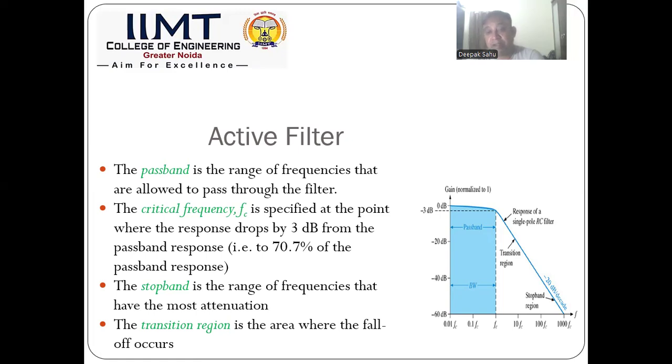And now there is the roll-off factor, which is actually our main issue, because the roll-off region after the cutoff frequency has to be very narrow, so that it does not incorporate or absorb any noise from nearby systems. So the roll-off factor needs to be high. The higher the roll-off factor, the sharper the slope of the filter, and a very refined cutoff we can obtain.